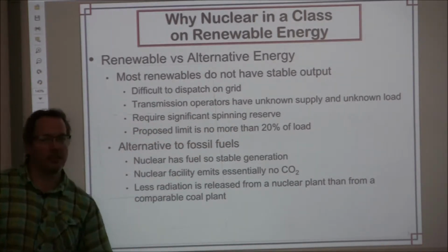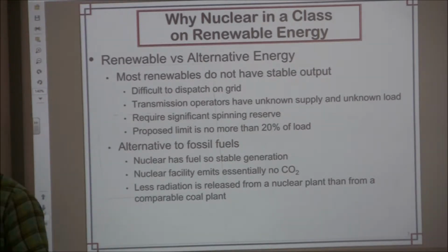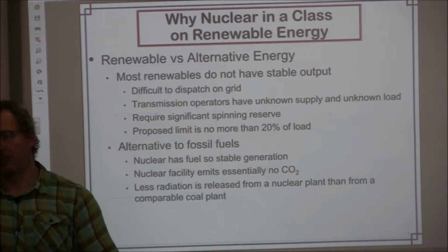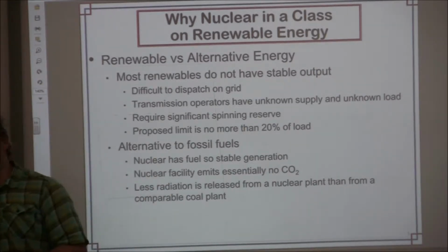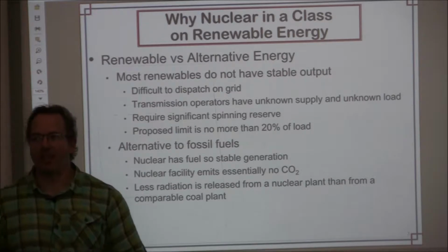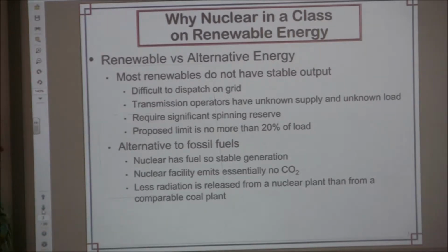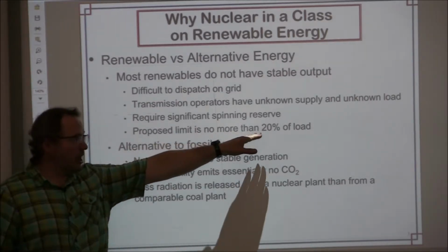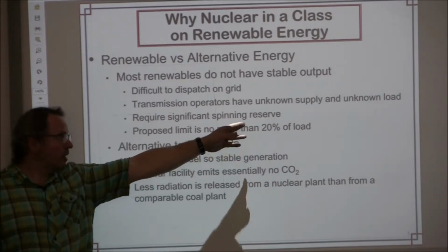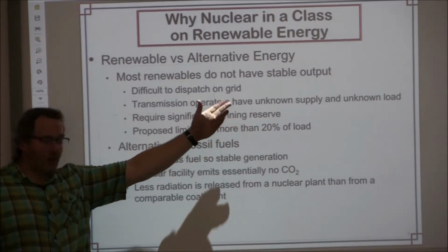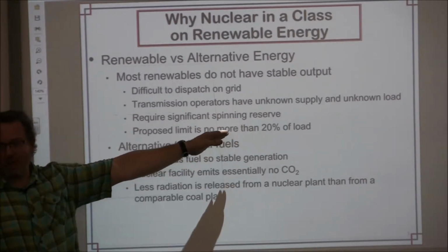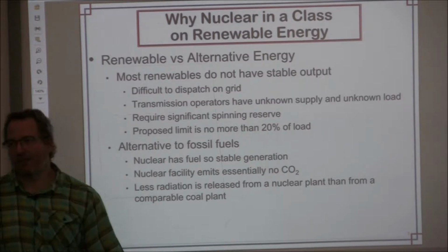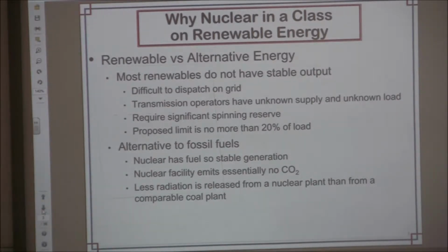Right now, if it's a non-dispatchable resource, wind and solar, or PV I should say, most people will tell you I do not want more than 20% of my generation coming from those non-dispatchable resources, because it becomes cost prohibitive, and if I lose a good percentage, say, I get a bad storm or something that really covers up most of my PV, or if the wind dies down very quickly for whatever reason, then I can actually have some customers losing energy.